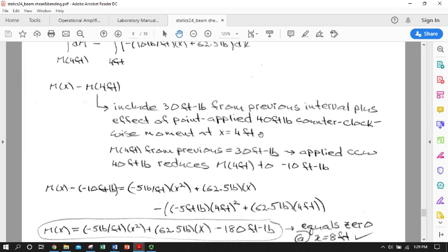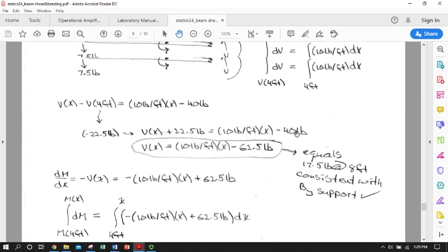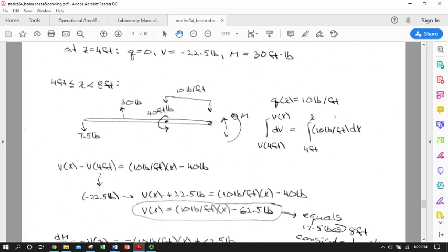And it's being applied in the counterclockwise direction. So what that's actually doing is counteracting the amount that's having to be applied here. So this moment here is actually opposing a clockwise net moment in the left-handmost side of the beam. Well, now we applied 40 foot-pounds counterclockwise, so this one only has to apply 10 foot-pounds now, and it goes in the other direction.